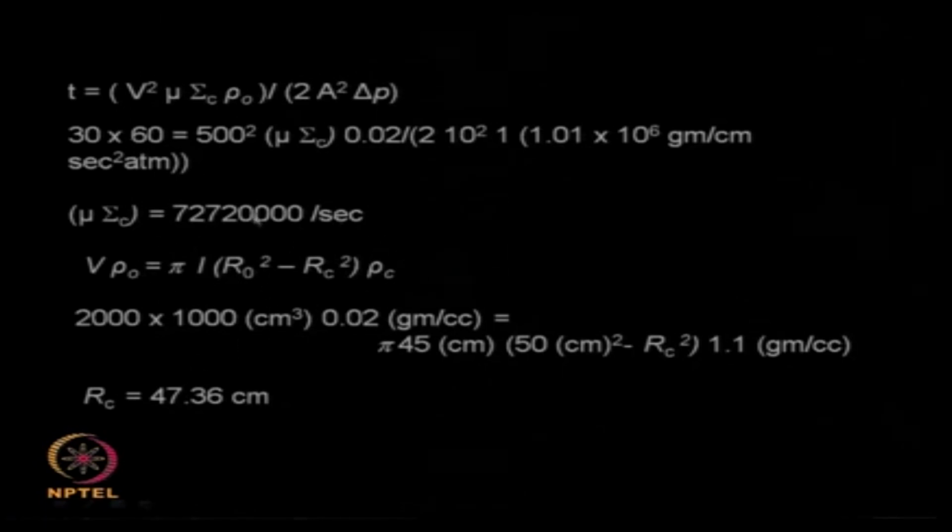So this equation is a mass balance of the amount of solids present in the slurry with the amount of cake that gets deposited in the centrifuge when you process this much amount of slurry. So by doing this balance we are calculating the level of the cake, okay, that is what is RC.